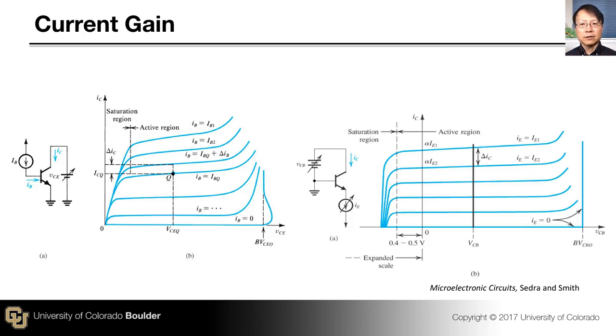So here are some examples of the bipolar junction transistor in an actual circuit. The left shows the common emitter configuration, where for a given input current into the base, I sub B, you monitor the output current, the collector current, as a function of the voltage that you apply on the collector.